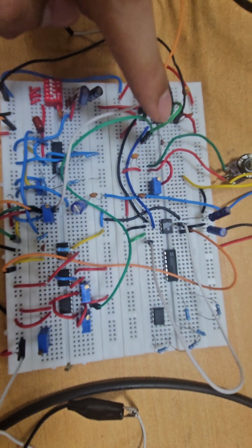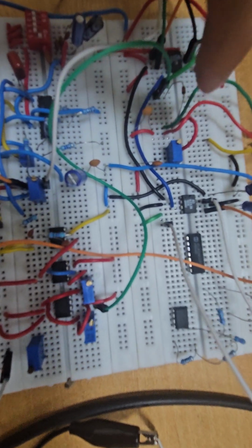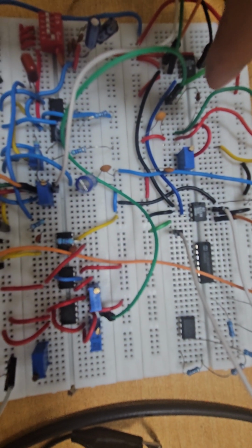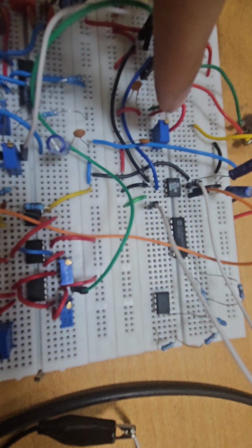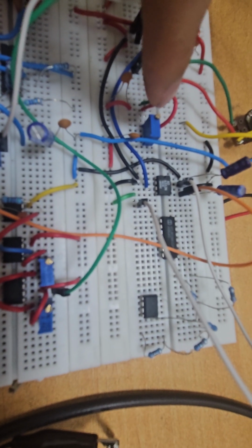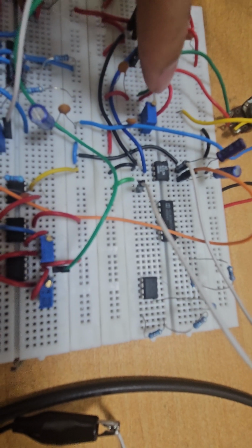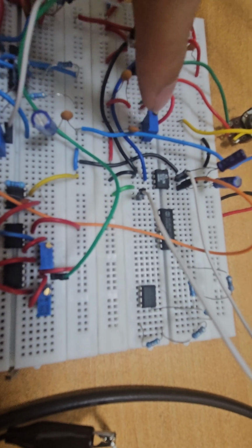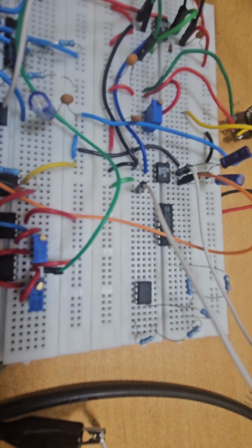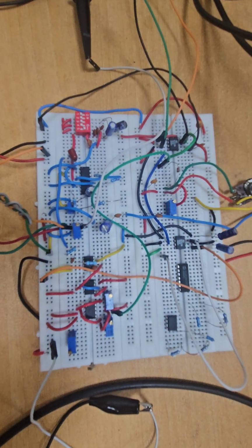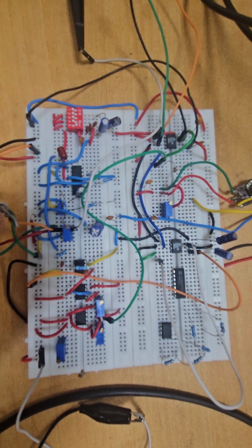Now after the envelope detection, I have implemented one low pass filter to filter out the ripples coming into the envelope when I detected the envelope. The low pass filter will attenuate the higher frequencies, so it will smoothen our message signal. At the output of this low pass filter, we can retrieve our message signal which was given at the input. So the explanation of this circuit is over.